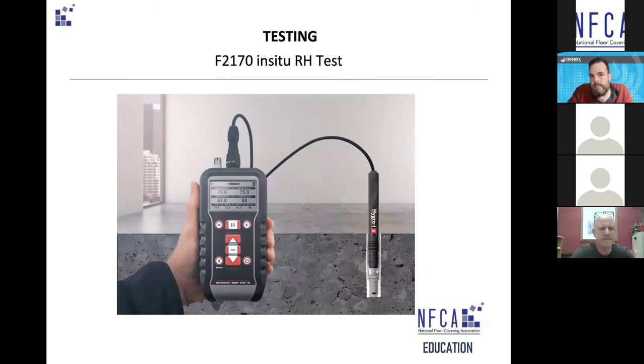So this thing of being 10 degrees from dew point is about the humidity. In other words, if you're below 85% RH in situ, it's quite reasonably presumed that you will not have moisture problems in that concrete, because you'll be below the humidity saturation level. So that's the purpose of it. That's where 85% came from, and it was written into all the Scandinavian standards for many years.